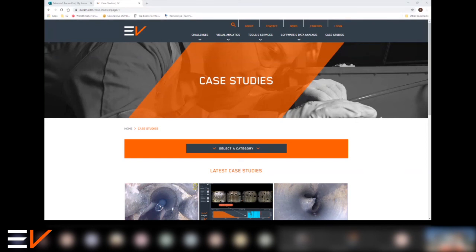I think, though, the most interesting development that we're working on, which we're about to field trial, and we have tools on the way to Canada at the moment for some early work on this, is what we call our hybrid memory system, where we're able to see one of the cameras, whether it's the downward viewing camera or one of the 4 array cameras, in real time. And that allows us to do very instant spot checks of what's going on and take a view of the well around us. But then on command, we can tell it to record all 4 cameras into the memory system over whatever interval we like.